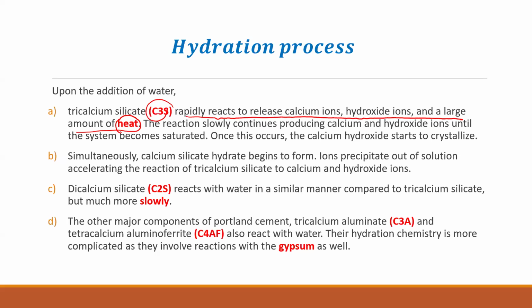Once this occurs, the calcium hydroxide starts to crystallize. Simultaneously, calcium silicate hydrate begins to form. Ions precipitate out of the solution, accelerating the reaction of tricalcium silicate to calcium and hydroxide ions. I will show you the reactions in a few minutes.